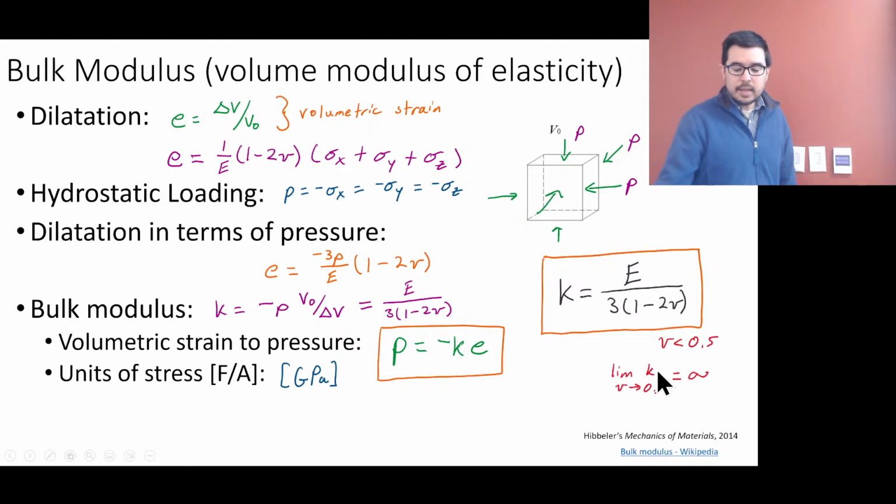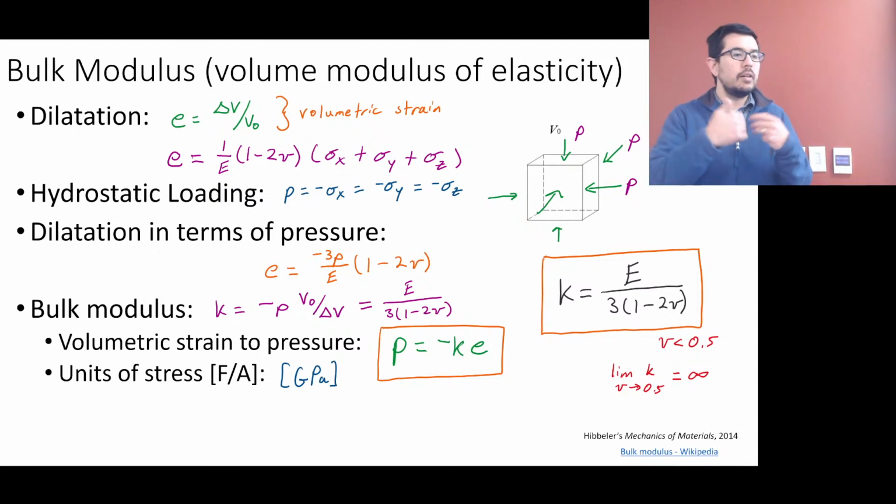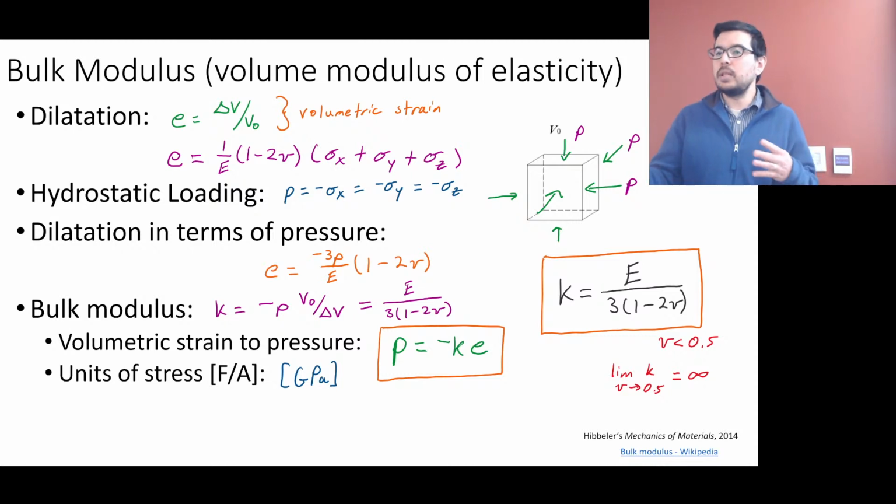Now, we did talk about the Poisson ratio and its values, and if you look at the video from Efficient Engineering, it also discusses what happens when you have negative Poisson ratios. But for the solid materials we'll be dealing with in this class, they're typically going to be positive and less than 0.5. If it were to be 0.5, what would happen?